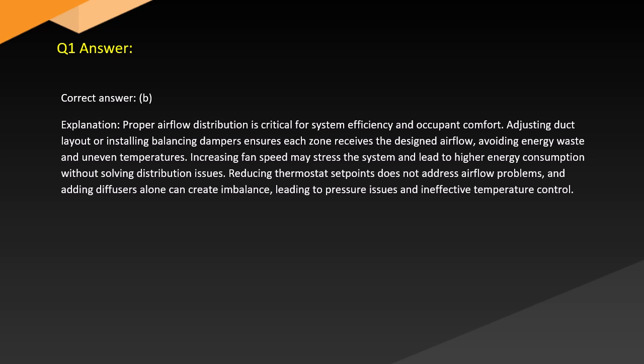Increasing fan speed may stress the system and lead to higher energy consumption without solving distribution issues. Reducing thermostat set points does not address airflow problems, and diffusers alone can create imbalance, leading to pressure issues and ineffective temperature control.